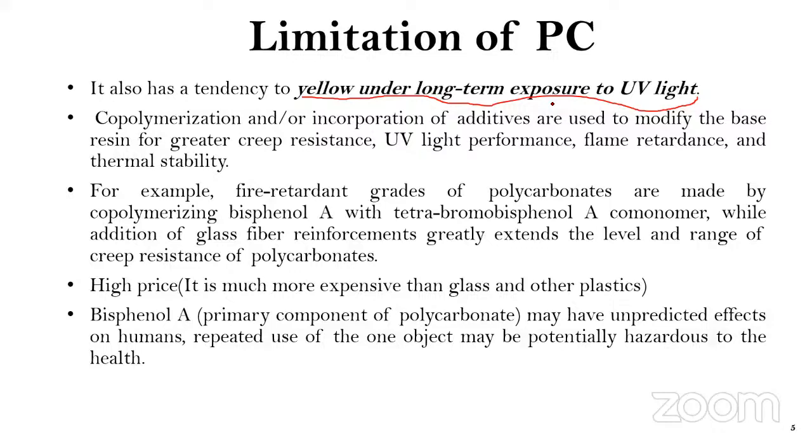And if that is also exposed for a longer duration of time to the UV, you see that they turn yellow. So for the maximum of the polymers that I synthesized, I'm not saying it occurs every time, but from my experience and observation, I found that the polymers manufactured from the polycondensation process are very less UV resistant.